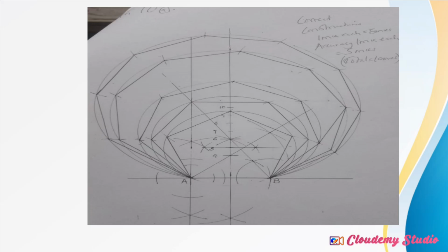Starting at point 5, I'll stretch my compass to point A, draw a circle that touches point A and B. If I draw that circle, I'll measure the distance between A and B, which is 50 millimeters, and mark uniformly throughout the circle. And if you do it accurately, you'll discover that the last mark will form the last point of that regular pentagon.